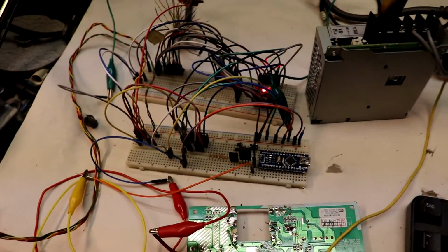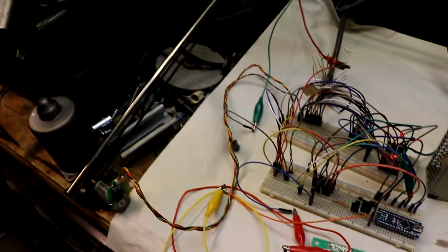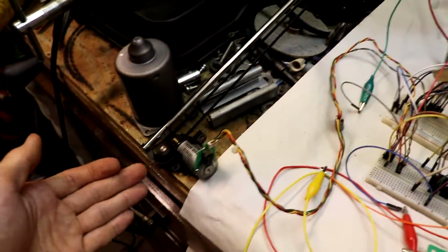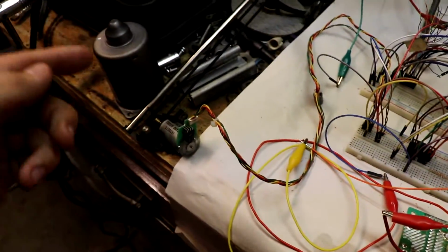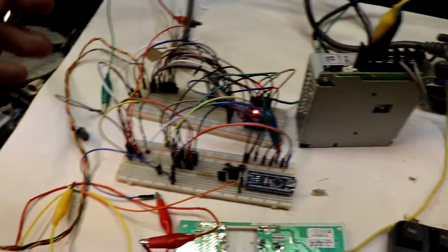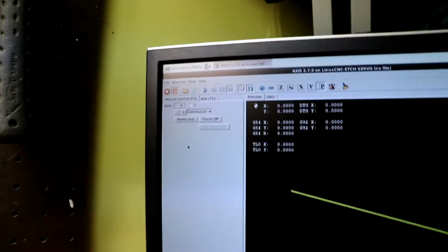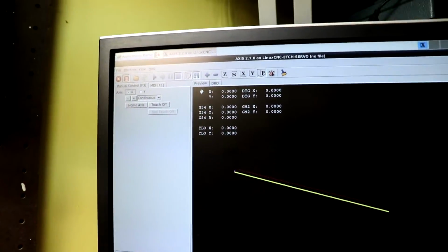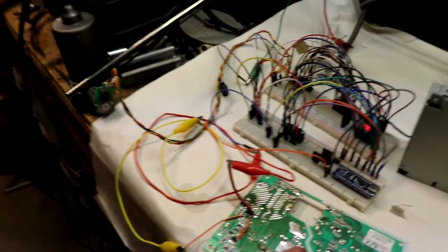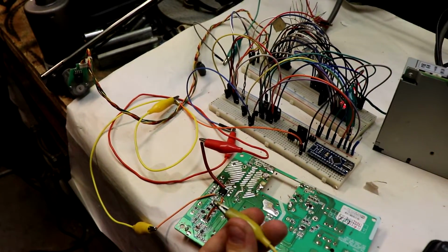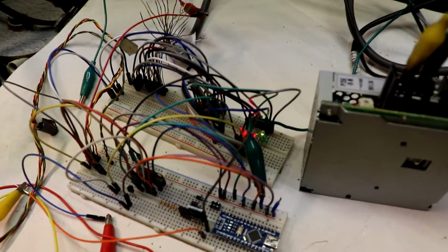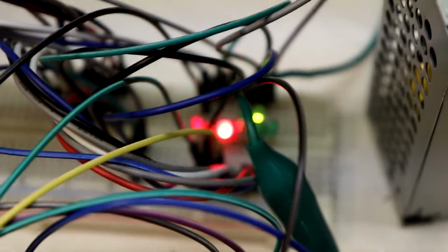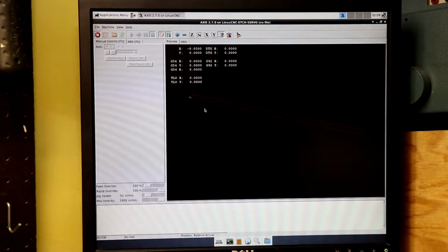I'll demonstrate this now. So I found that to make things work and for the motor to not run off on you, first enable the encoder. Then you have to turn on your machine. The last thing you should do is apply power. And there you go. Okay, so once you open your program, you will see something like this.